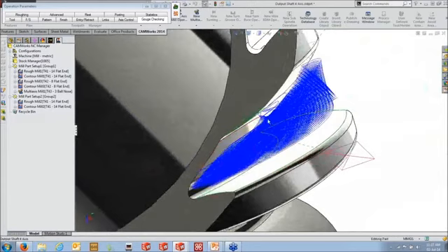and that's one of the more common issues. Like a lot of the toolpath you'll see is actually finishing toolpath, but actually getting the actual material out can be somewhat of a problem. So that's basically how you use the area roughing. We drive it between two faces. These two faces right here actually control the limits left and right. The upper surface and the lower surface down here control the actual volume.